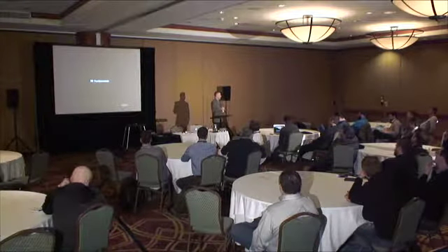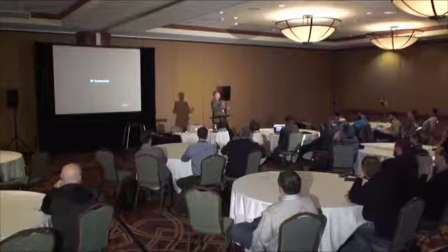So I'm still very big on actually doing a physical, whatever you want to call it. It may not be called a survey, but I need to visually eyeball the site. I want to look for things like the firewall that used to be an exterior wall that's now an interior wall, or a true firewall that may not show up on the floor plan. I need to see where the freezer's located, how things are laid out, the rest of that. So I'm looking for anything that jumps out at me as something I need to investigate further. So if I need to go back and take some measurements, I can do that beforehand.